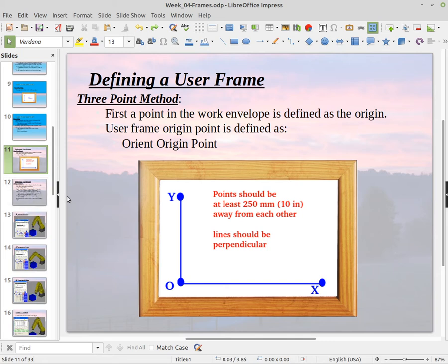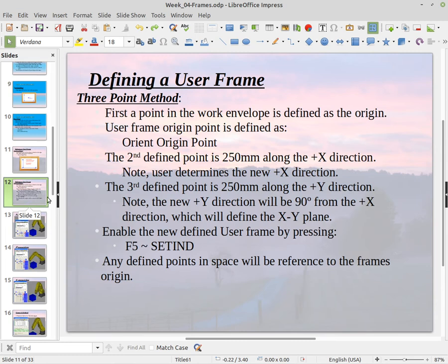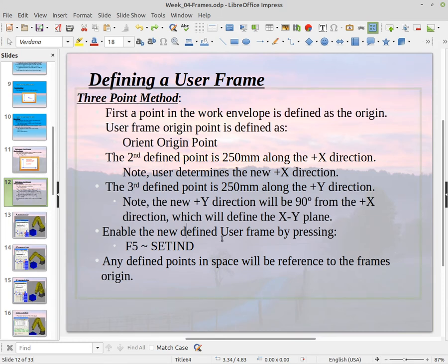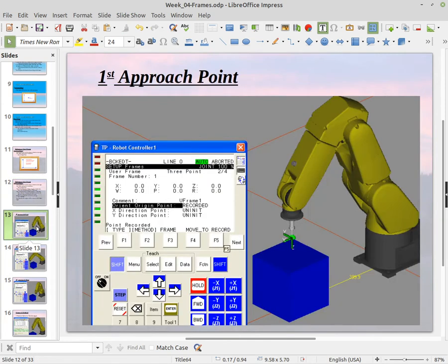It basically remaps them back into the world frame, because the world frame is the robot's true point of reference. And so all these points inside of these user frames are just math, and it's just a mathematical transformation to describe where they are in the world frame. Alright, but we have to just go in and save all 3 of those points. Once we do that, we can then define that user frame as a point of reference for jogging and in our programs.